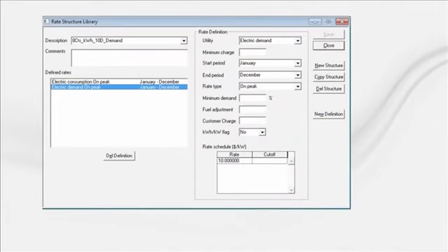The next step is defining the utility rates, including demand and consumption charges. Now, this is a really important step. Remember from previous E&Ls that 2 same price chillers, 1 constant speed and 1 variable speed, can differ in design kW by more than 15%, and that's what sets the demand charge, even if it only occurs for 15 minutes in the year. So we define the chilled water plant.